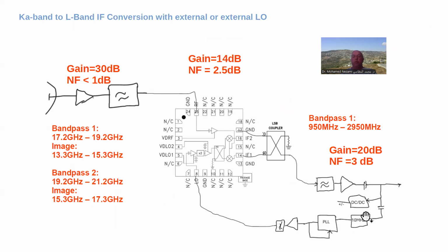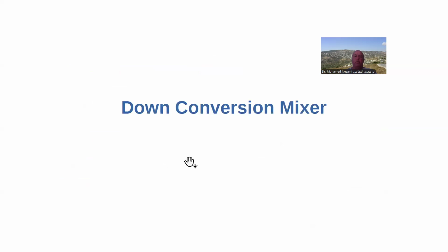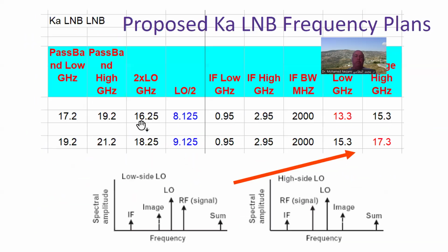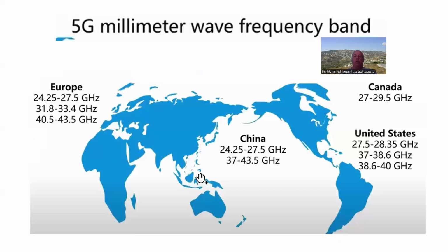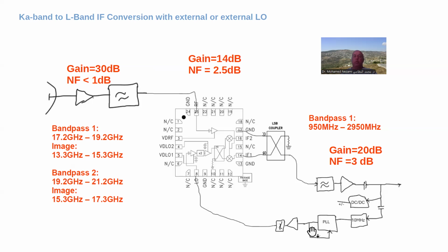This is going to be a whole part of my series, just to design this portion here and analyze it as a system. So we come in here at one half of the frequency that I would need, which is half of 16.25 and 8.25, which are these values. And these are so close to each other that you can do them in one PLL chip.